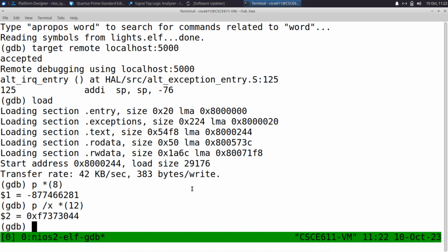So if I were trying to do bulk data transfer, it would take about 7 cycles for every 4 bytes of data that I read from the Avalon, which is pretty abysmally slow if I'm trying to do high-speed copying, right? So I didn't get to, but you can try that if you want.